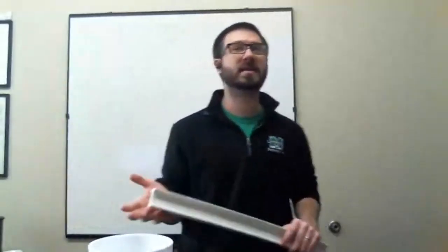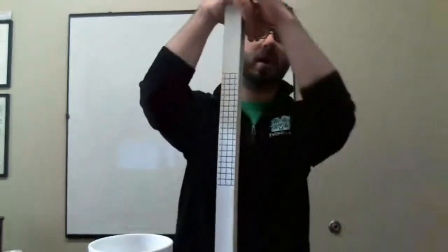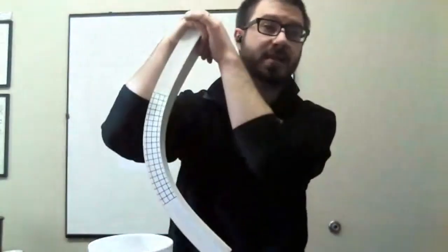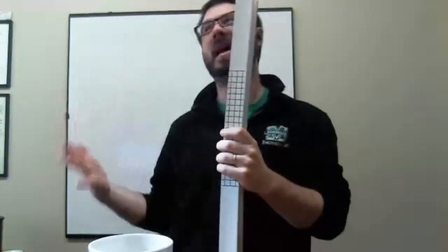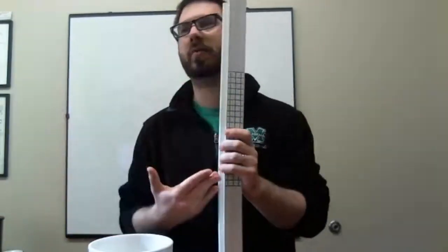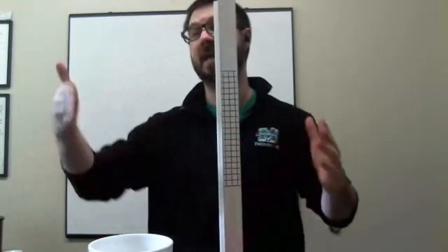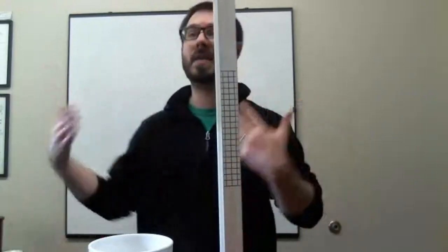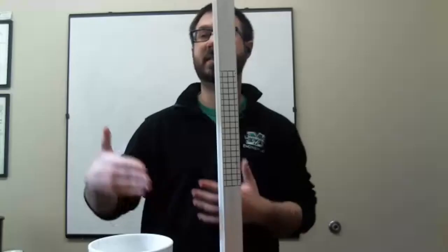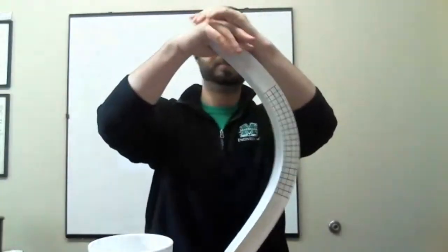The way you said that was excellent, because what you did just there is you defined two limit states. You defined failure under general compressive stress, where we might ask ourselves what the limit would be. Maybe the limit is when the metal reaches its yield stress. So compressive yielding would be a limit state. Another limit state might be compressive buckling. Here's the column, bam, it buckles.